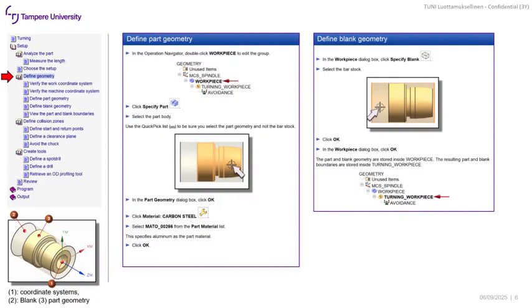So of course you need to first make one of them transparent to be able to work with the whole piece, and then you are defining what is the workpiece, what is the material, and then what is the blank or raw material. Another option is that in case we are only facing a simple raw stock geometry, like for example, also in this case, only a normal cylinder, in those cases, we can directly define the raw stock in the software.